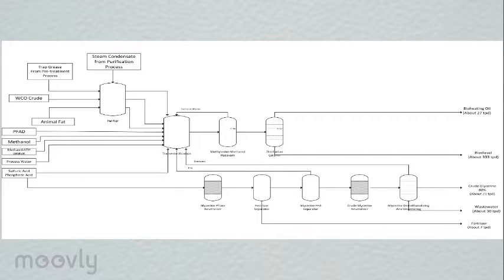The process continues with the high content of free fatty acids, which includes palm oil fatty acids and grease trap oil, directly transferred into methyl ester by esterification using high pressure, high temperature reaction conditions without catalyst. A certain amount of free fatty acids as well as fatty acids recycled from the byproduct acidification, from the glycerin FFA separator, and the oil phase from the purifier are esterified using methanol under acidic condition and ambient pressure in a batch process. Catalyst is used in the transesterification reaction, which is possible under moderate temperature and normal pressure. The catalyst used is potassium hydroxide and methanol.